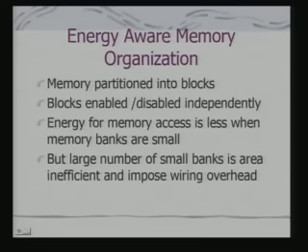So far we have looked at use of cache, okay, to speed up, and we said that using multi-level cache, you can also have energy optimization. But what about actually memory organization, okay, in terms of blocks? Because I told you that if you are driving a long bit line, that would actually lead to more energy because you need more current to drive a longish bit line. So, if you divide your memory into blocks, what happens?